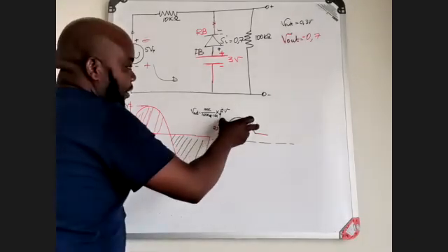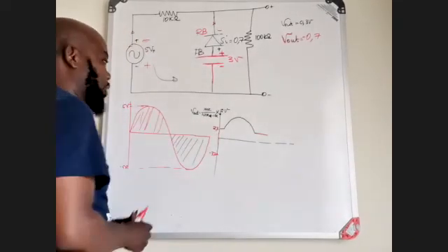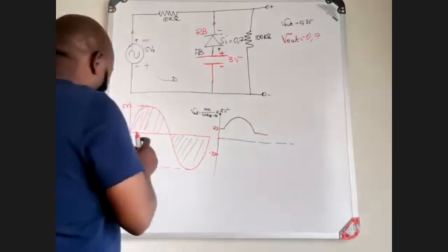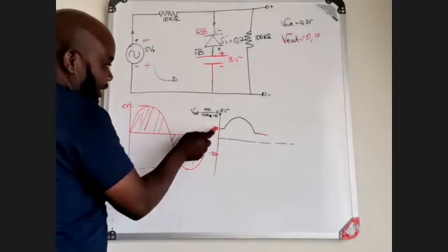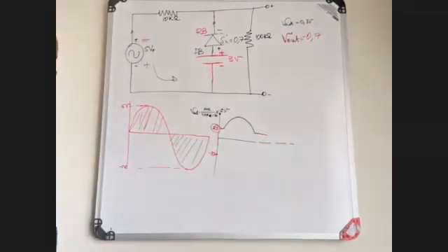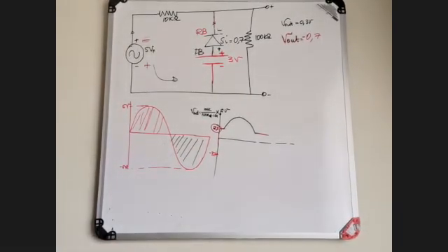Then you end up with that small signal there, which means now your circuit doesn't start at 0. Now it's going to start at a certain voltage there. This is when you are biasing. Also, this is when you are limiting your input signal with a bias voltage.